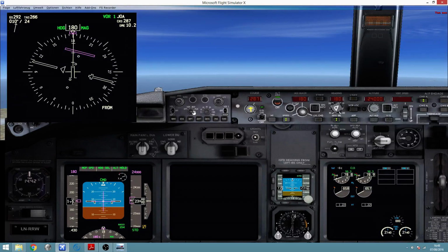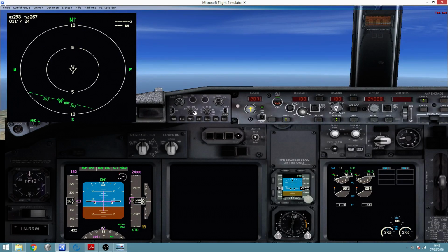There is the first one, which is APP, that we will only use for the ILS approach, as you will later see. Then we have the VOR, which is the one that we are currently using and the one that you will use mostly for your simulation. And then we have two others, which are for area navigation, which is something a lot more advanced that we go through in the master, which are map and plan.